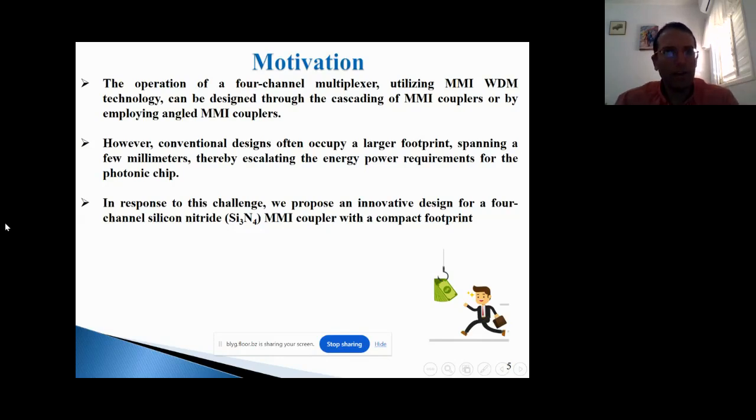So today you can use a cascade of couplers to increase the bitrate, but the penalty is it will take you millimeter space from the footprint. So this is a big challenge. Also another problem, of course, is the back reflections that we can deal with by replacing the silicon with silicon nitride, and also integrated tapers to reduce the back reflections, which is very problematic because if I have a strong back reflection in my system, it will damage the signal. You will not get the communication, and of course it will affect the speed.